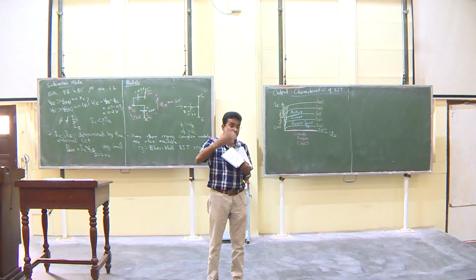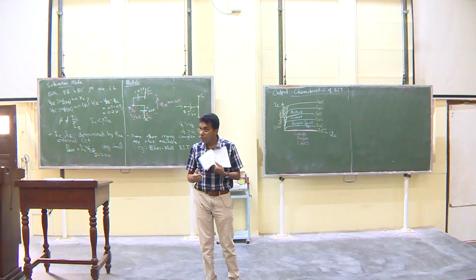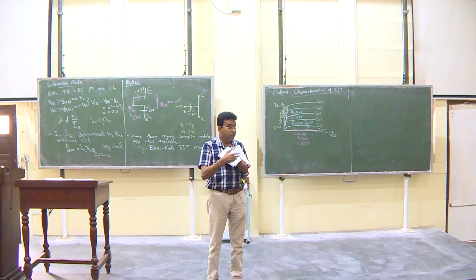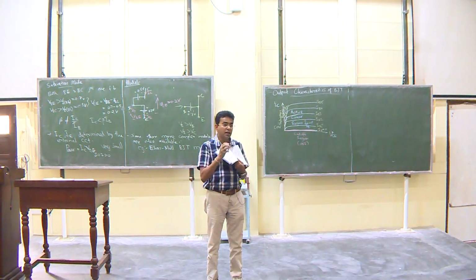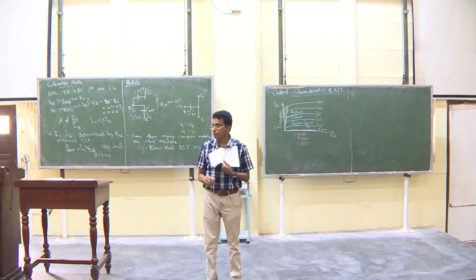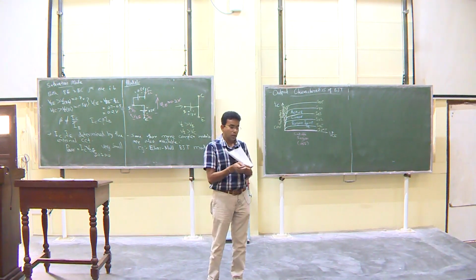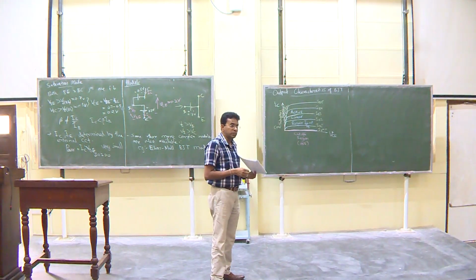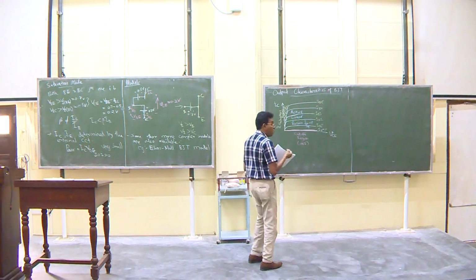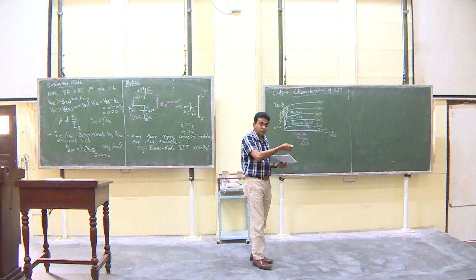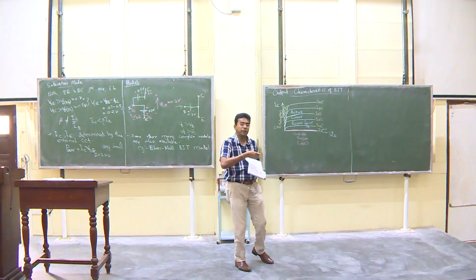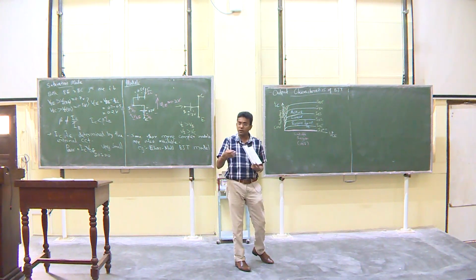As temperature goes up, beta will increase further and further, increasing IC even further, and what will happen? There will be too much heat and it will burn the transistor. Okay, so that is called the breakdown region, right. So, there is a breakdown region where VC times IC is a constant, which is the power, and that is the power at which the external environment can dissipate heat. If it is above that, it will start burning.